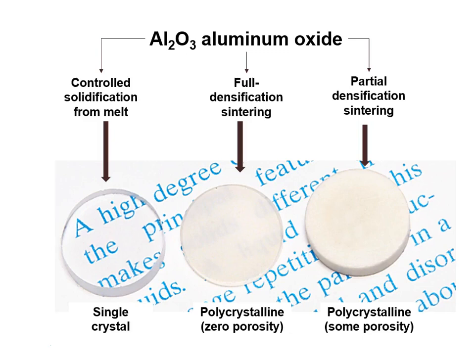If you get rid of all the grain boundaries, such that you have a single crystal, there is nothing to scatter the light. Light goes right through and you have a completely transparent structure. So if you look at it from the standpoint of optical transparency, say you need a lens or you need a window on a light source, not all aluminum oxide is the same. You definitely want to process it into a single crystal. So this is our example of processing matters, depending on the property you want.